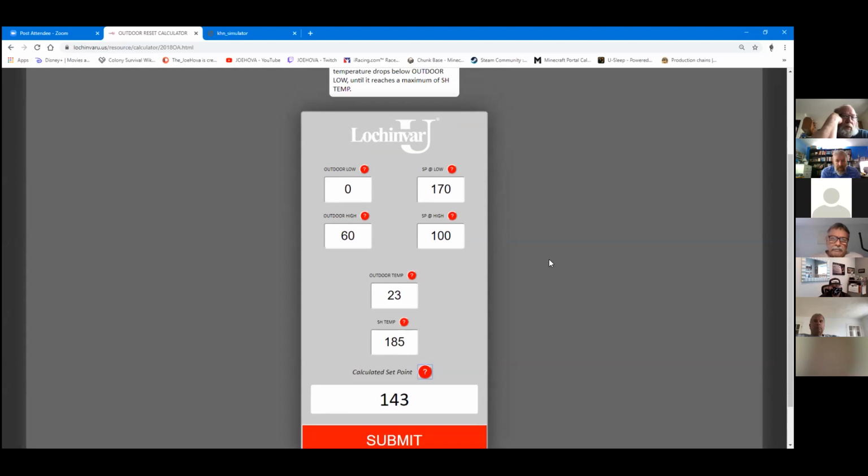One of the greatest things about this control also is, even though we take your SH temperature set point away as a set point, we convert it to a high limit. So let's say you have this scenario, but you're going under concrete. You want the aggressive nature of the curve. I mean, you want it to change temperature. This is a 70-degree rise in temperature right here.